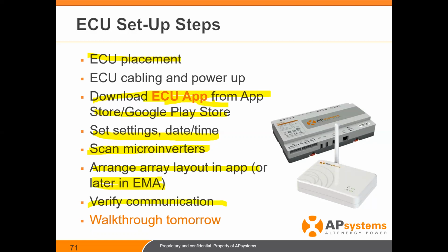And to verify communication, like I said, the power of this tool, and you'll see it tomorrow, is to be able to know on site. The installers now have information in the palm of their hands. Everyone on your team and on that job site can dial in and look at the device and verify that, yes, all the inverters have been installed, all the inverters are communicating, the DC connections are good, AC connections are good, and power production the day of installation. Like I said, the last thing I want you guys doing is rolling trucks tomorrow for a problem that could have been noticed and solved today. So tomorrow, we'll learn a lot more about that.